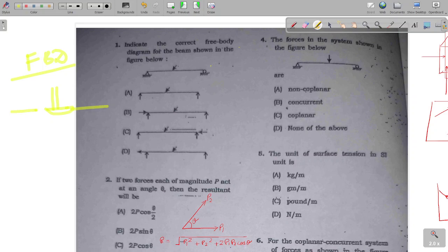So suppose this is a fan. My drawing is very horrible, so forgive me for that. There is a fan that's connected to a rod and two hooks in your roofs. So if we cut it here and just depict the load that's acting through that, this is going to be your free body diagram. It is a free body diagram because we have freed the body and are just showing the loading that's acting through those supports.